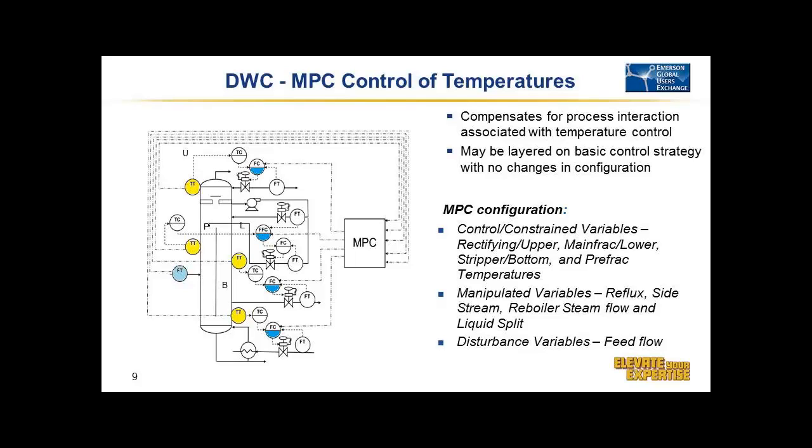But where a dividing wall column gets more confusing is we have a top of the wall section. And so you might think that we're just going to do a 50-50 liquid split or let it fall naturally, but you actually get a better separation by changing this wall split. So we found the optimal to be about 30% on this side and 70% here, but we actually have it set up that this can be a control variable for us. So we have a total trap tray that we can pull the liquid out into a vessel, and with 2 control valves actually make that split.